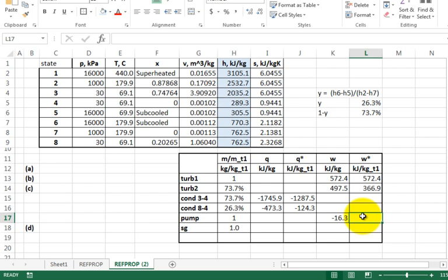Let's see how close VdP is compared to the 16.3. Make sense? So how about if I just put right here, V times dP. All right. I have, where's my specific volume? Isn't that my specific volume at state 4? And I multiply it by the change in pressure. It takes it all the way to 16 megapascal. And it's starting at 30 kilopascal.